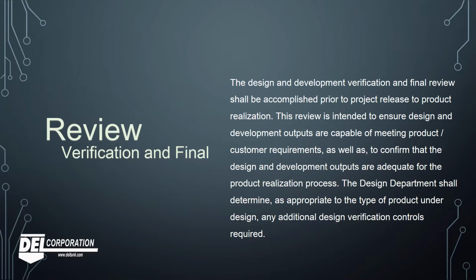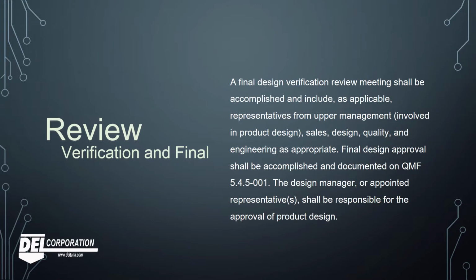The design department shall determine, as appropriate to the type of product under design, any additional design verification controls required. A final design verification review meeting shall be accomplished and include, as applicable, representatives from upper management involved in product design, sales, quality, and engineering as appropriate. Final design approval shall be accomplished and documented on QMF 5.4.5-001. The design manager or appointed representative shall be responsible for the approval of product design.